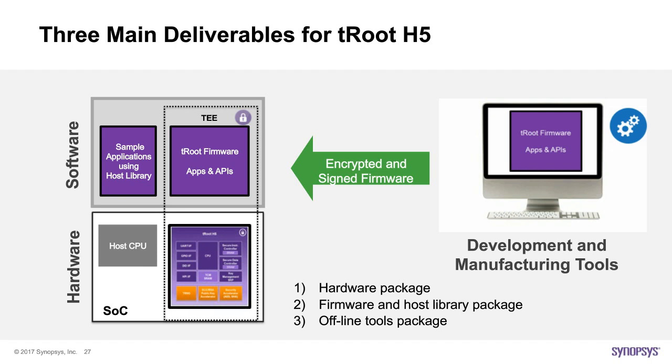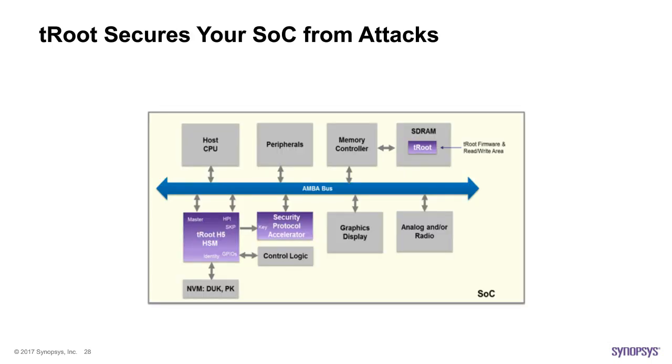tRoot H5 is designed to offer high-grade security solutions to help eliminate the many potential threats to your SoC. For example, malicious host software can be eliminated by using the secure boot functionality provided by tRoot H5. In this particular case, you can even use the ROMless feature to enable secure boot. tRoot H5 will verify the image prior to running it on the CPU.